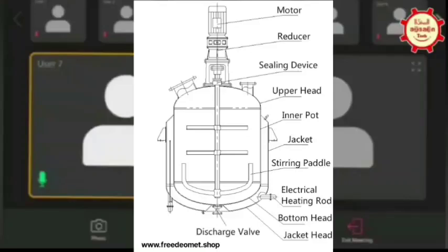Minimum, we just used to keep 50 mm. Normally we keep that because an arrangement to hold the shaft needs to be provided at the bottom. To weld that arrangement at the bottom, a minimum of 50 mm is required, because normally for the weld gap we give 50 mm.